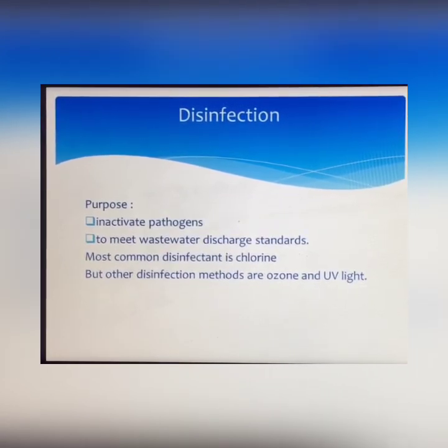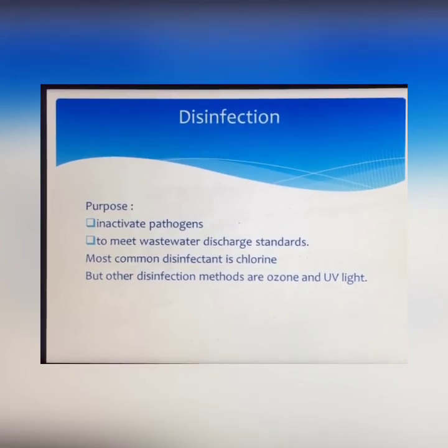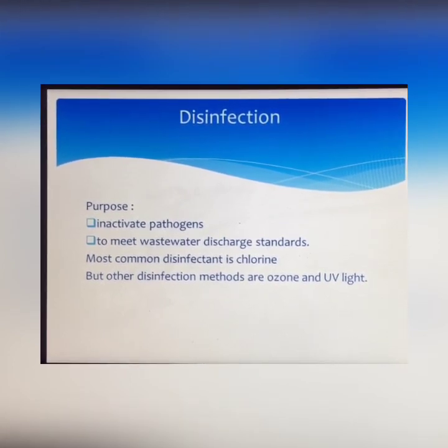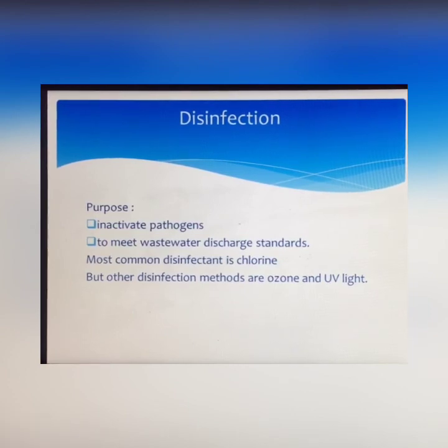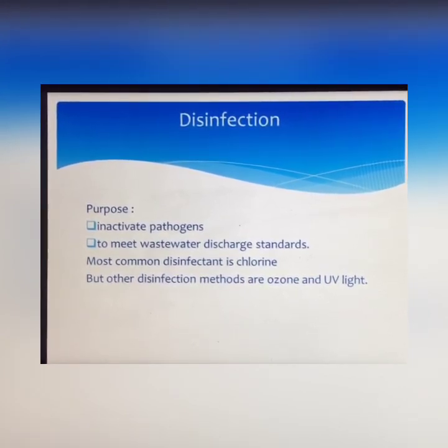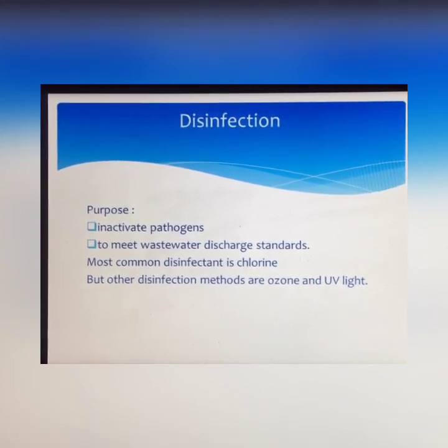Disinfection. This is the last step of wastewater treatment, whereby chlorine is added to inactivate pathogens and to also ensure that the water meets the wastewater discharge standards. Chlorine is not the only disinfectant that can be used. There are other disinfection methods, for example, ozone and UV light.